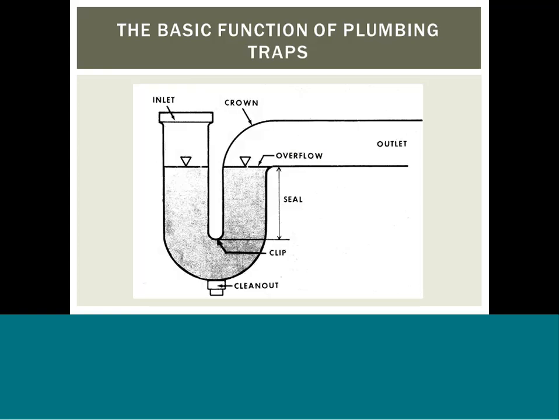In accordance with national and state plumbing codes, traps have to be placed under just about every plumbing fixture, which includes sinks, bathtubs, and toilets. These devices trap a small amount of water at their bottoms. It's the water in each fixture that acts as a barrier to smells, gases, insects, and bacteria. Because P-traps are designed to be low points under a sink or other fixture, they can often become a collection point for hair and other objects.